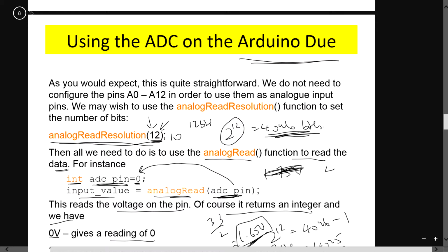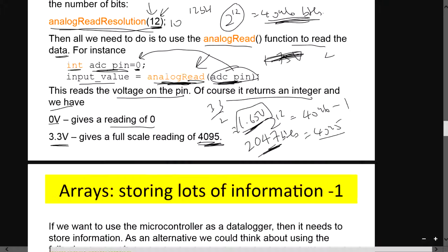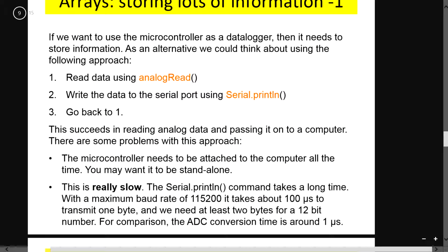All these codes are what we set up in order to read the analog signal. Once you have read your pin, you want to print, so you need to use Serial.println for whatever you read. And you keep on looping. So you read, you print, and then you loop back to reading again and print a new analog value. For example, you receive 1, and you print to the serial monitor that you've received 1 analog signal.